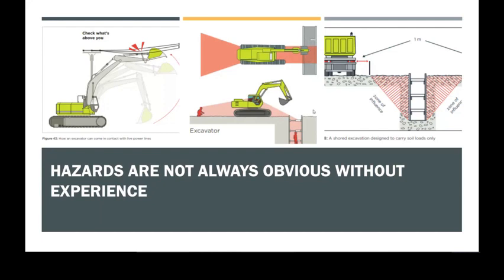So you've got to work together. If you want him to stop, you have a hand signal. So put your hand up, stop, whatever it is. He puts his boom down, turns the thing off, or turns it right down so he can't bump it and turn it on, and then you walk up and talk to him, or he jumps out and talks to you. So you've got a communication plan in place beforehand. Also, you don't want other random people sneaking up behind him, because he might swing around to put some dirt in the thing or whatever. He might back up, run someone over, they're dead. It could be a 20-ton digger. Might just be a little 2-tonner, but even that could do quite a lot of damage to someone.